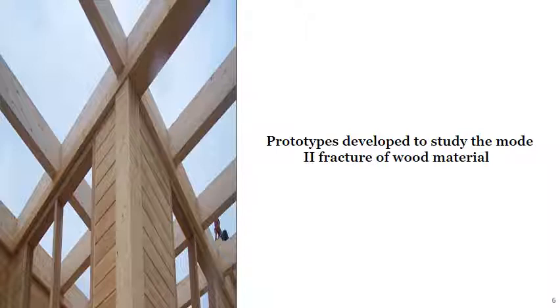Kramer and Pugel used a compact shear specimen to characterize the Mode 2 toughness of southern pine. In the LT plane, we also find that Combs used the compact tension shear specimen designed by Richard for isotropic materials to estimate G2C. All these tests were well carried out, but several difficulties slow down a deeper investigation in these prototypes. One quotes among the observed obstacles, the experimental assemblies which check the purpose of the test are very difficult to carry out. Also, a bifurcation of the crack is in general observed from the beginning of the test. For this reason, only the three tests mentioned above will be considered in the following.